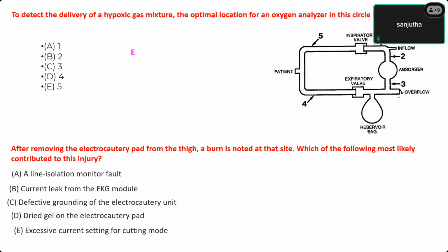Defective grounding, sir. Dried gel, contact. Dried gel, exactly, correct. So when you use the sticking pad, nowadays many hospitals reuse the pad which is meant for single use. Repeatedly using the same sticking pad causes drying of the gel, and that can be the